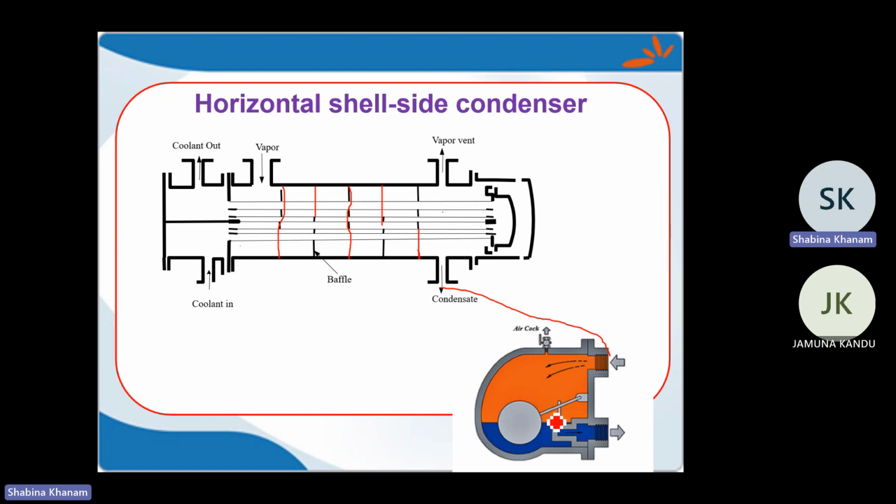The condensate which settles at the bottom, as it keeps on filling this space, will keep the balloon up. If liquid is available up to here, the balloon will be up to here also.